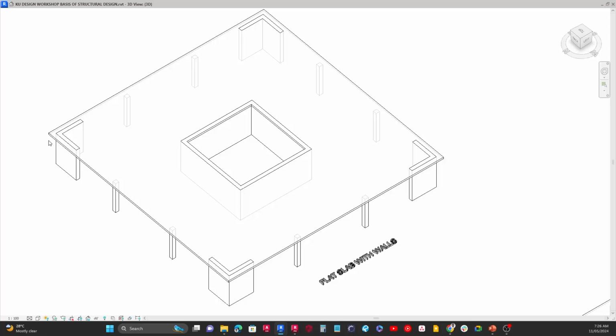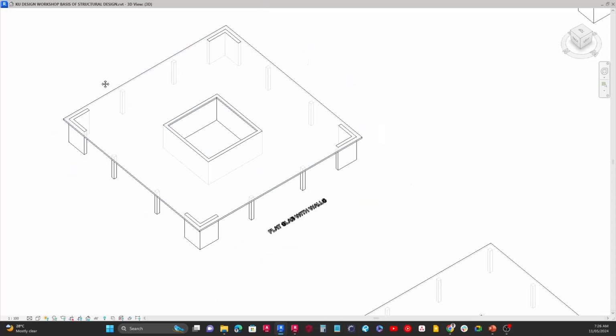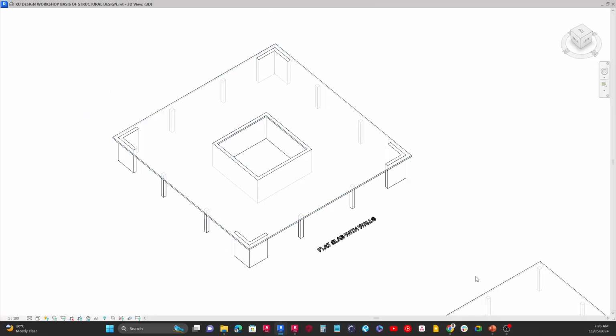We also place them at the sides to brace against winds and those kinds of forces. For instance here, if the wind is heavier in this direction, so let's say it is blowing like this, the walls will be placed like this. So let me go ahead and delete. The walls will be placed like this. It is quite similar to how I showed the column illustration earlier. So if the wind is blowing in this direction, designers will place the orientation of the walls in this direction. If the wind is blowing in this direction, for instance, now let me go ahead.